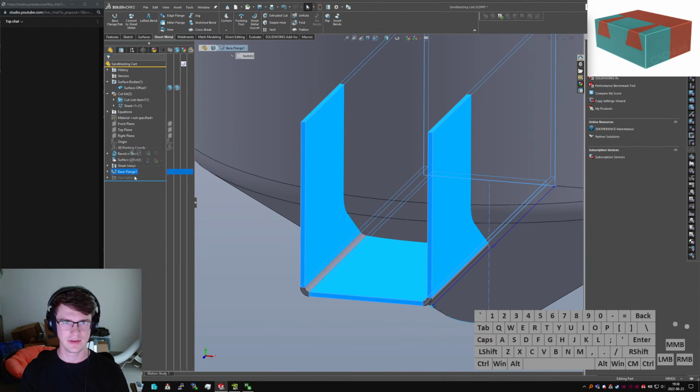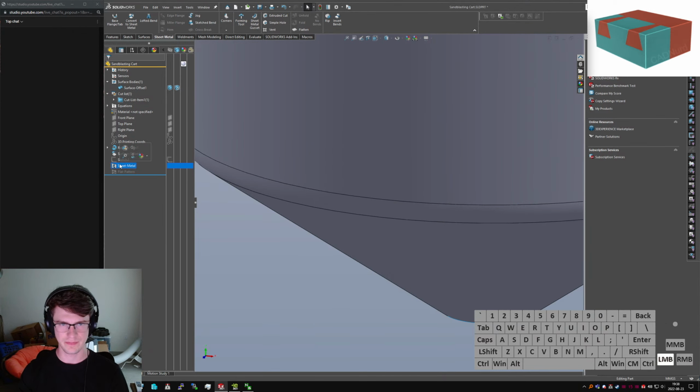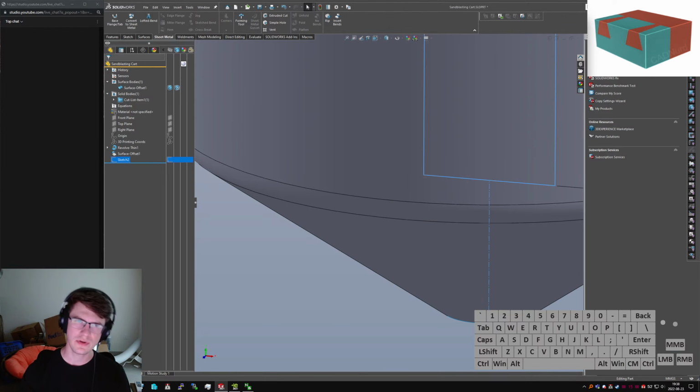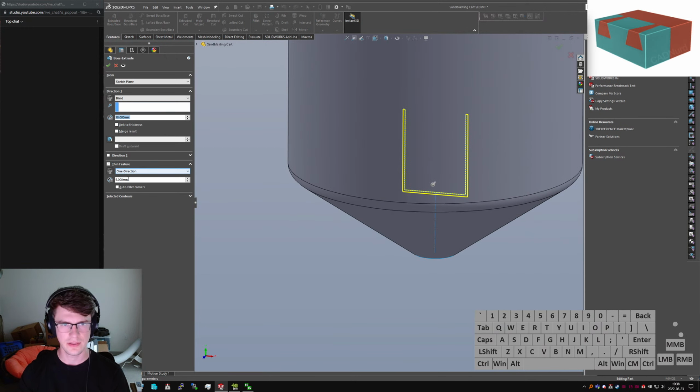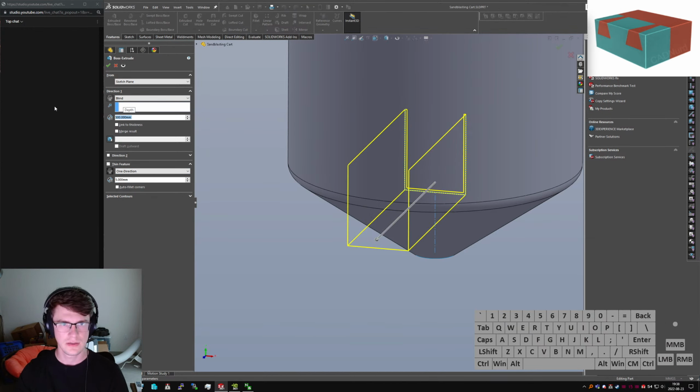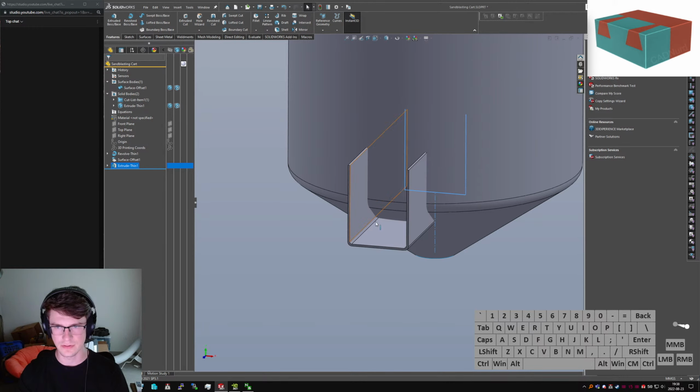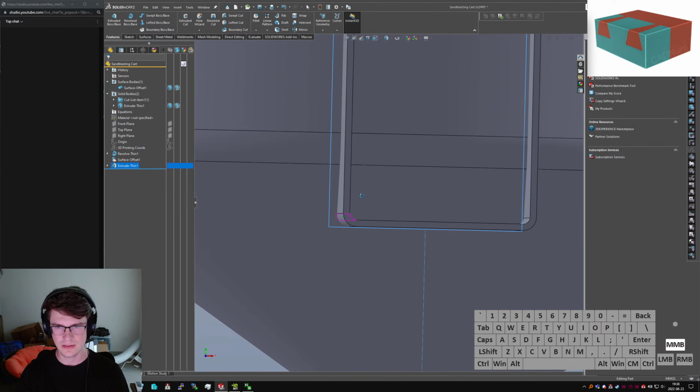Okay. So we'll delete this base flange, and the sheet metal folder. And probably the sketch too. Well, and we'll keep it. Okay, so extruded solid, thin feature one direction, make sure it's on the right side, blind, half a meter, seems about right. And when it says autofill at corners, is that gonna do, it does, nice.